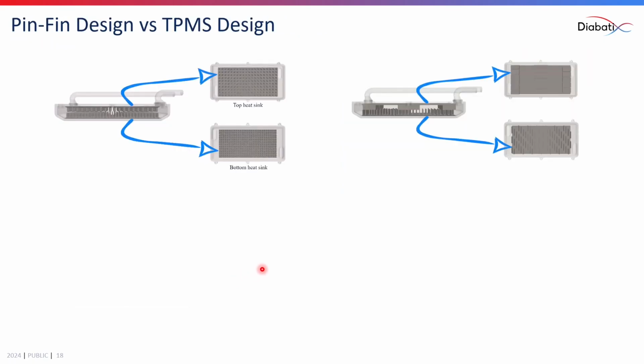I would like to show you a couple of pin designs. Here you can see a pin design on the left-hand side. Our optimizer went through the same process and found the best combination of pins that can be obtained for this heatsink, where you can see about 500 pins generated at the top of the optimization design domain and about 1000 pins at the bottom. The same exercise also shows the different types of pin designs which are created for the same setup.